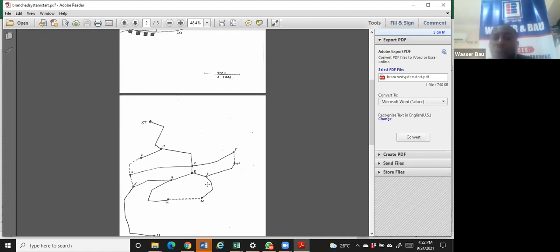Okay. So finally, we have done node 13, we have done node 6, we have done node 11. Now we are doing node 7. And I said before you get node 7, you must have done node 11 and node 6. Okay, so what will I do now? For me to get node 7, I have to add up this value plus this value and see if there are any houses connected to itself. I hope nobody's confused there. Node 7 will now be all the houses connected to it plus the houses downstream.